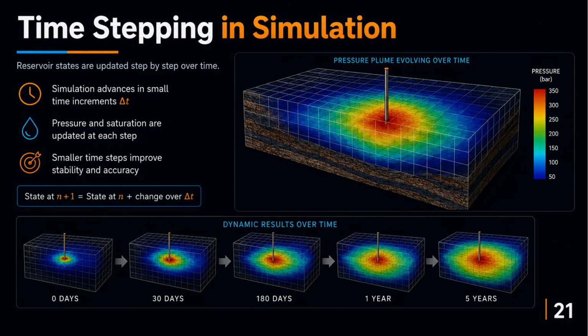In practical terms, time stepping affects both accuracy and speed. If you simulate CO₂ injection over 30 years, you may not need daily time steps during quiet periods. But during the start of injection, shut-in, breakthrough, or operational changes, smaller time steps may be necessary. A strong modeler understands when to trust large steps and when to refine them.